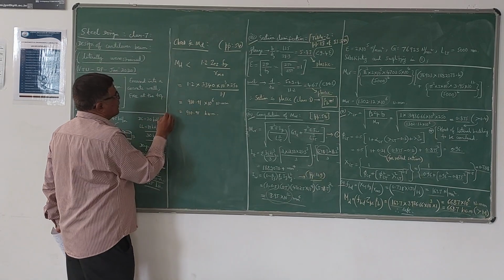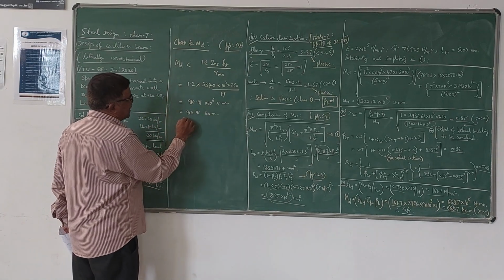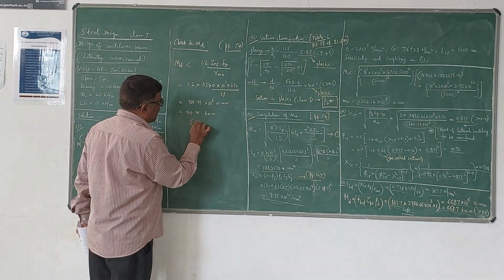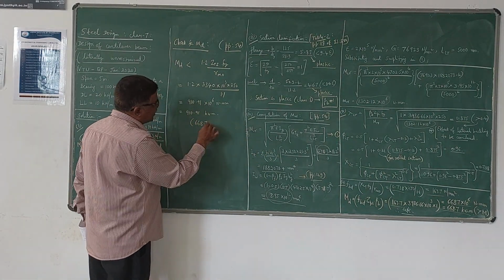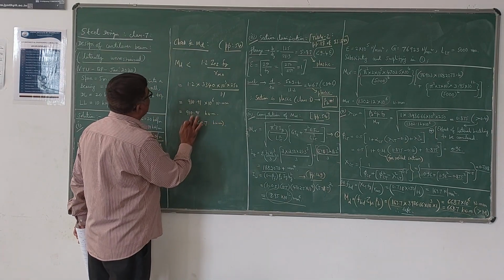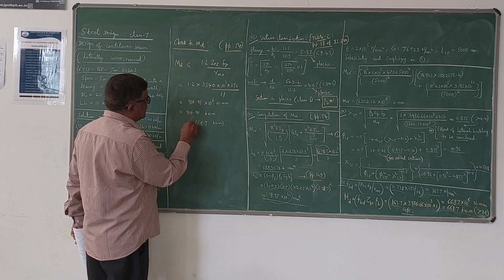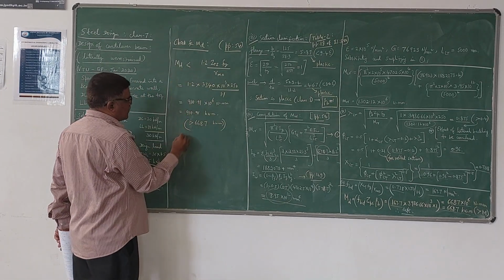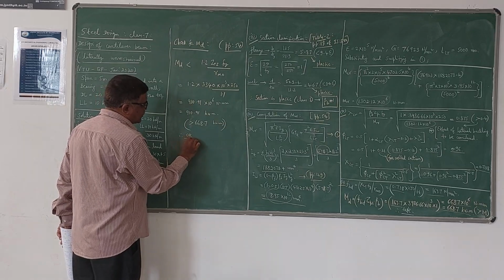So definitely your MD value is below this. Whatever you have got, 668.7 something, please check for that value. You may get a slightly different, slightly less value. You can see that this is greater. Since this value is greater than this, therefore okay. So this is the check we have to do.